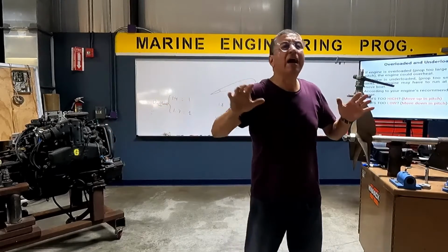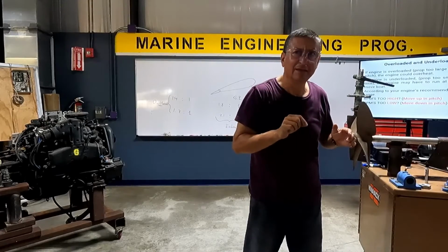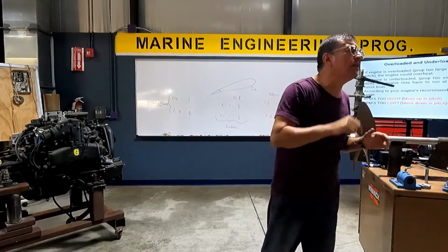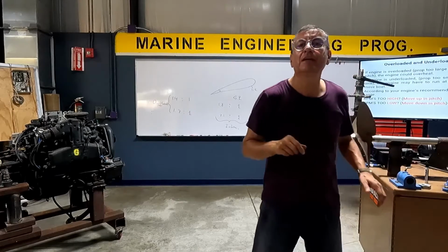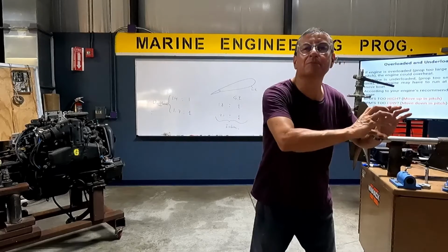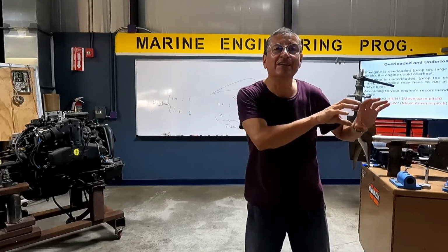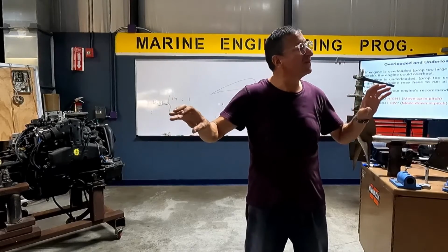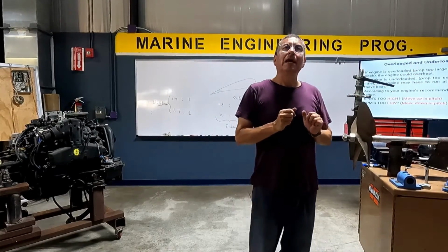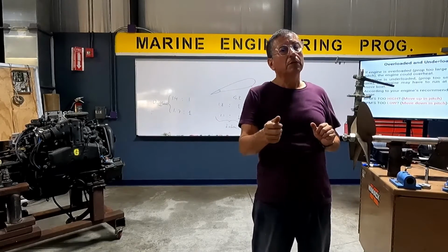What about fifth? Low torque. In some cars, instead of the number 5 you have the letter D. What is the meaning of that? Drive. It's direct, the same RPMs as the engine, no reduction, in fifth or sixth in some cars. In first gear, high torque, low RPMs.